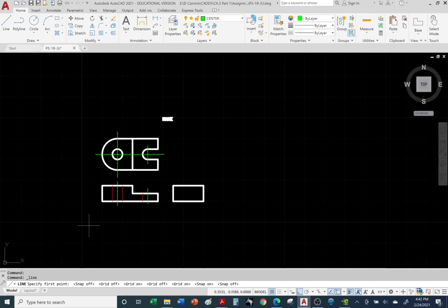Okay, close to 0. If I turn on snap, you can see whole numbers. So in this case, it's whole numbers for my grid. If I go to the origin, that's 0, 0, 0. Now there is a Z-axis. So we do have a Z-axis that's normal to the surface. That's why it's showing me XYZ coordinates here on the status bar. So the first one is my X, my Y, and Z is normal to the surface.